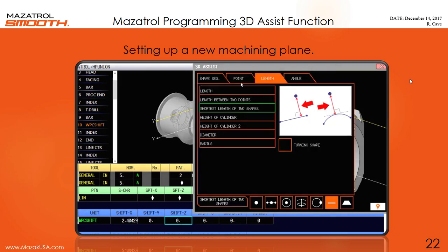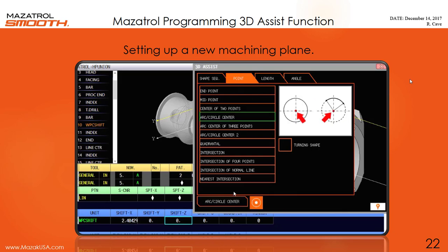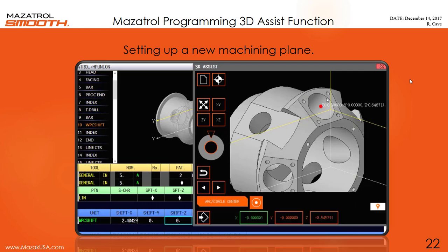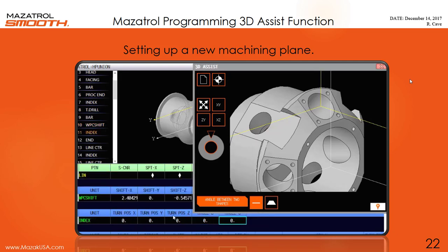Once again, I go back to point, arc and circle center, select that arc again, highlight Z in this case and hit input, and I've moved my 0 up to that point, but I still have to rotate the angle. To rotate the angle, I need an index unit.